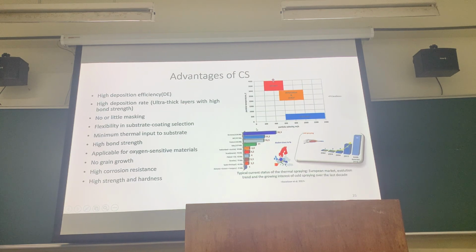All right, so advantages of cold spray. A lot of things that cold spray has. One of the things I just want to highlight, compared to thermal spray, as I expressed, is that it's very good for those materials that are easily oxidized. So copper, for example. You should remember that when people say, hey, you want to spray copper? Please use cold spray. All right.